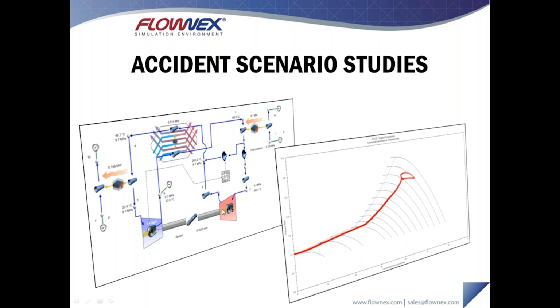So for example, if the turbine was producing more power than the compressor was consuming, we would have an increase in the speed of the shaft based on the inertia of the shaft, ultimately doing a moment balance on the shaft, calculating the angular acceleration and calculating a new angular speed. This is then used to calculate the response of this entire turbine compressor train.